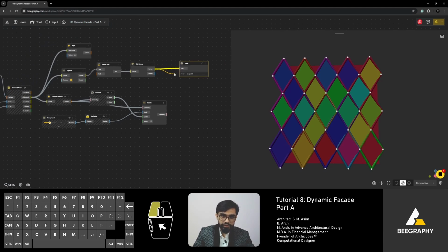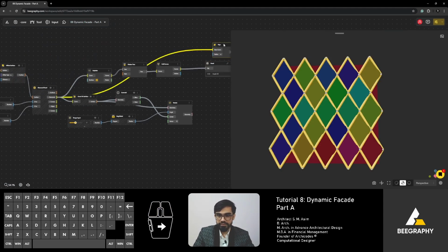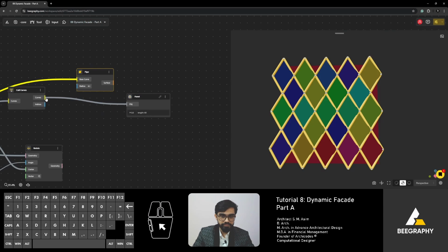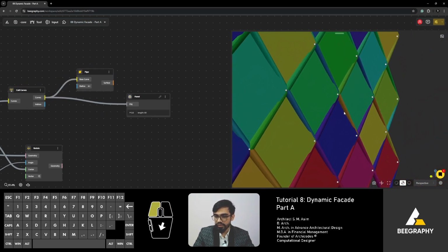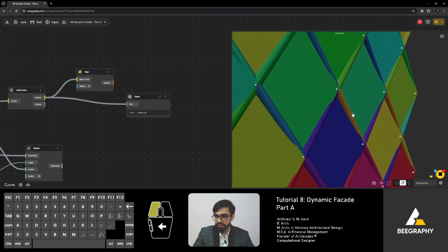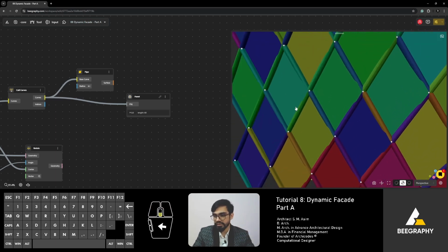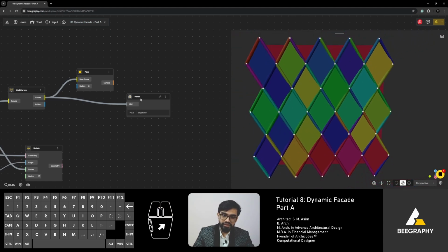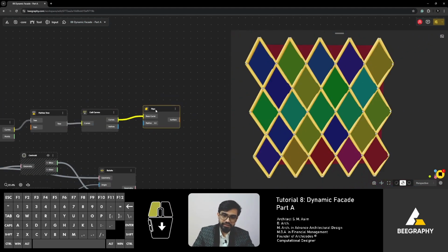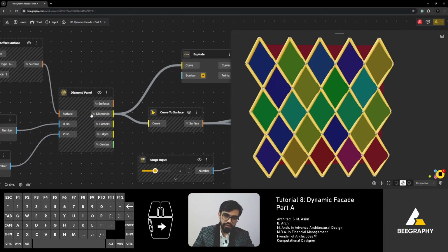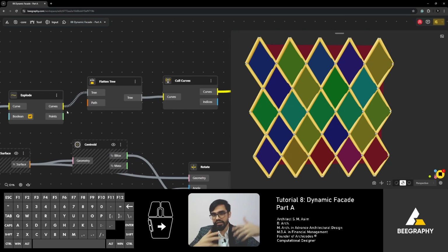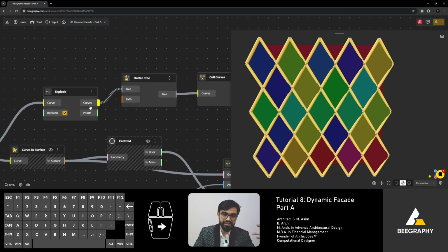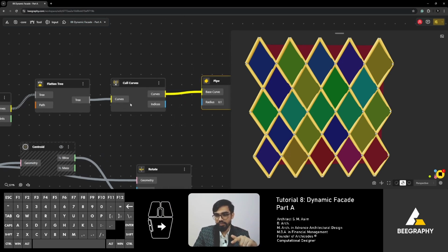Now we put this into our pipe system. And instantly you will be able to see that there is no rendering issue now. You see, there was rendering issue because two pipes were coinciding with each other. All right, so this was really nice. So in this case, I explained how we can explode curves, a polyline, then how the data is structured inside it, and then why I flatten it, and then I remove the duplicates.